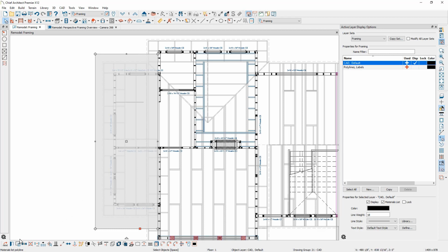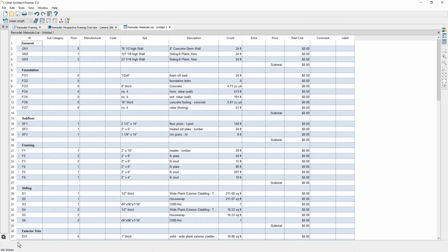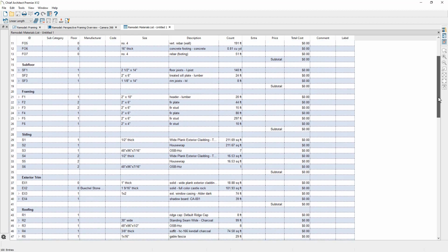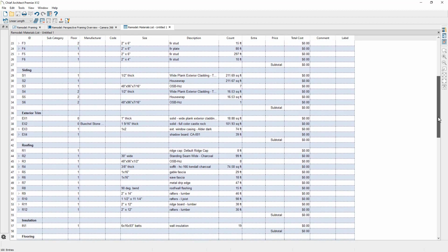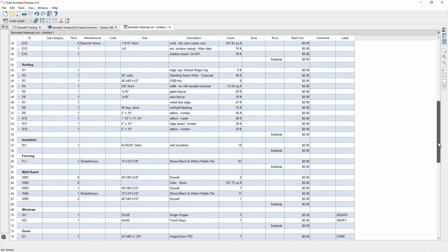Now that you've created this materials list polyline, you can execute this at any point by coming into your lower edit menu and selecting calculate materials from the polyline. This generates a spreadsheet-like format, and as you scroll down into the materials list, you can see all of the components that are making up this new addition for your project. You can type values into the pricing. So perhaps for your drywall, if we just used a number of $25, you can then calculate exactly how much material that would include and do a pricing.